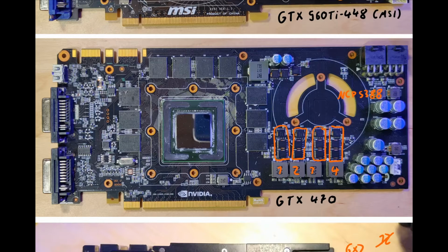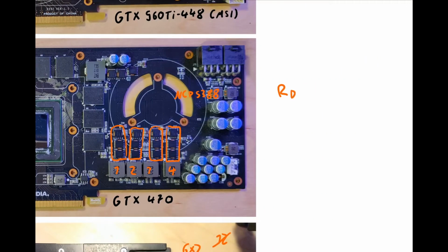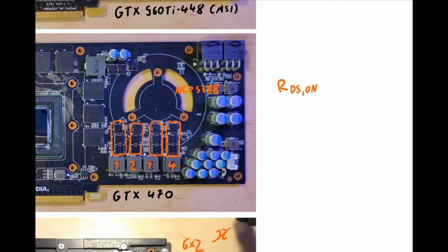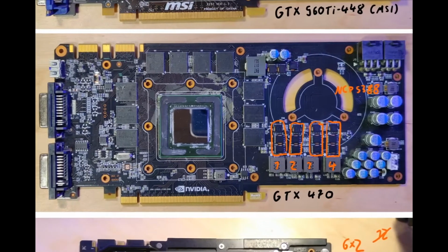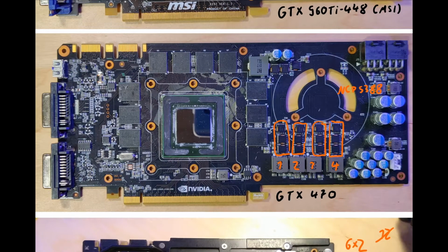So basically what you have to know is the low side MOSFET is the more important one, because it handles a lot more current. If you look up a datasheet for a MOSFET, for your high side MOSFET you want it to be fast, and for your low side MOSFET you want it to handle a lot of power and have the lowest possible RDS(on) resistance. The RDS(on) is the resistance the MOSFET has when it's turned on. The higher your RDS(on) is, the more heat the MOSFET will put out, and the more power will get wasted in the VRM. That's obviously bad, because when MOSFETs get too hot, they blow up. And when MOSFETs blow up, especially the high sides, you will introduce short circuits, and you will basically have a dead graphics card pretty fast.